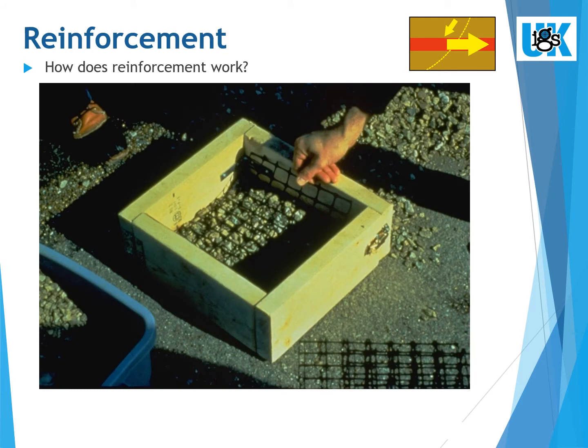By contrast, reinforced soil structures are internally stabilized. By layering grids or textiles within a fill body, the self-weight of the fill soil and any surcharge applied generates a tension in the reinforcement.